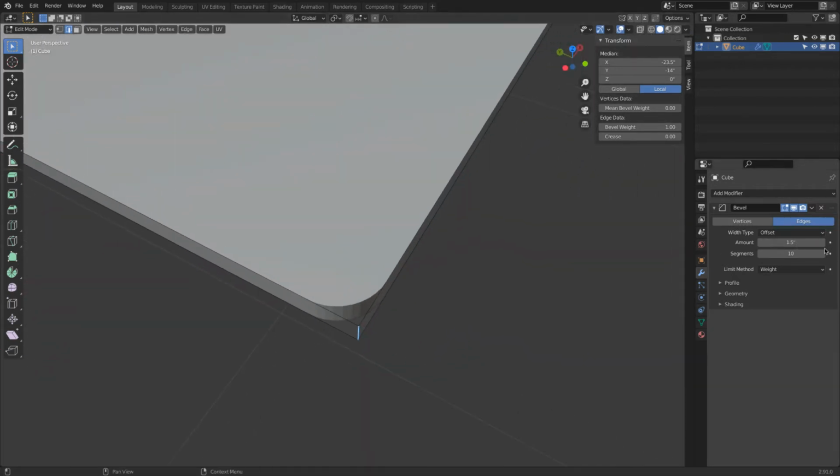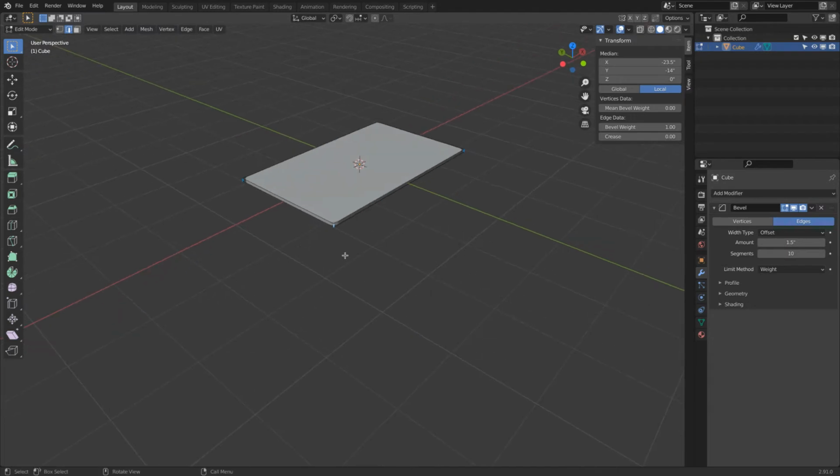With segments, what's the correct number? Well, we can type in 100 if you want to. Looks super round, but is a little bit overkill. In Blender, what we do here is do very fast concept modeling. So it doesn't have to be super precise. That is not the goal of doing concept modeling here. So something like 3 obviously is too coarse, but maybe 10 looks actually pretty decent. Specifically when we zoom out a little bit, you don't even see the facets.